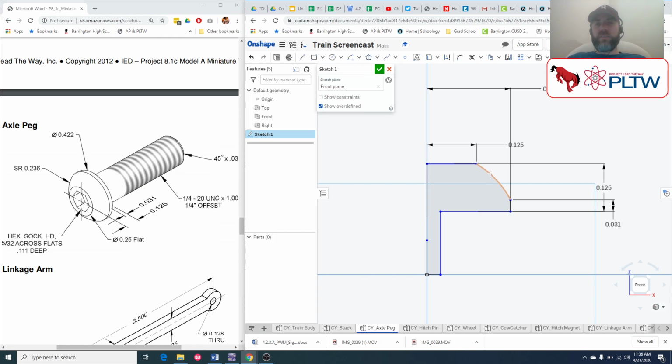Here's where I think I find that it's going to break. If I put in a dimension here, you see it says 0.236. If I try to actually type in 0.236, because it's got like 0.445 in there, I think it's going to come up all red. Yeah, you just can't solve it. So something is slightly off there. So I'm just going to hit Control Z, undo that, delete out that dimension. I am going to dimension it, but since it's coming in at 0.236, and I might not even use this part, as you'll see, I'm just going to leave it as whatever that default value is.